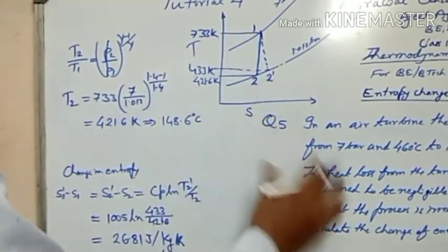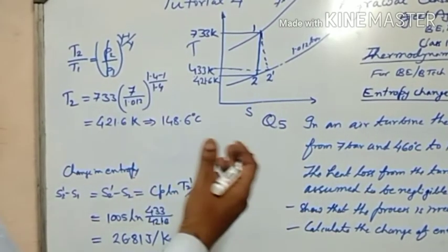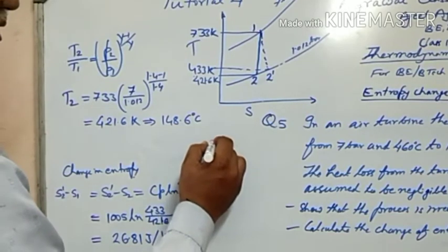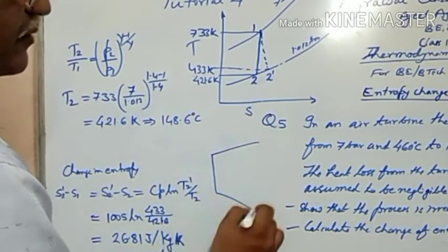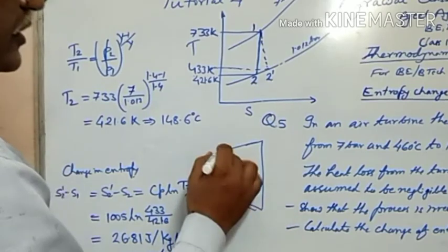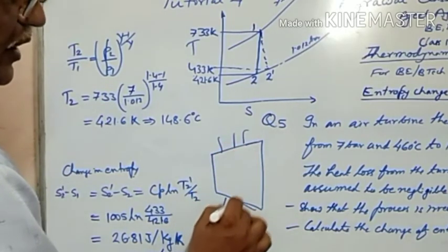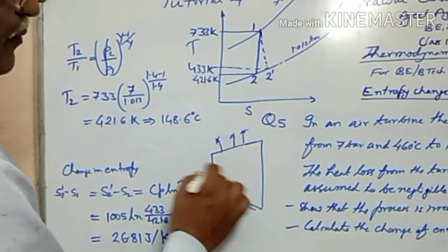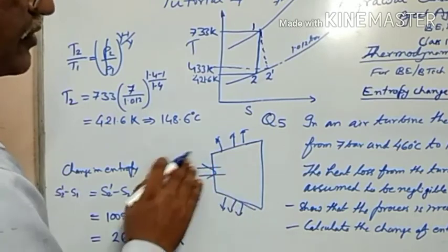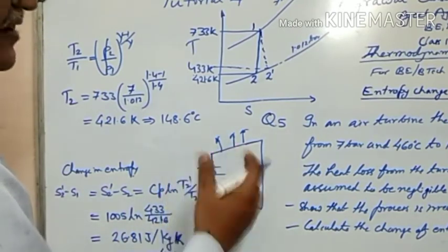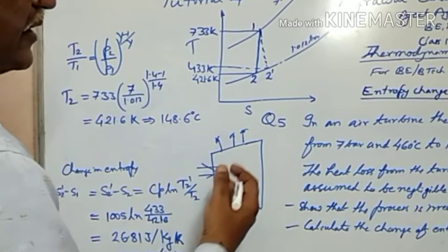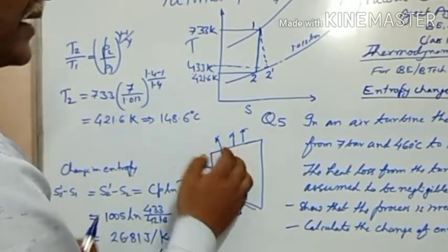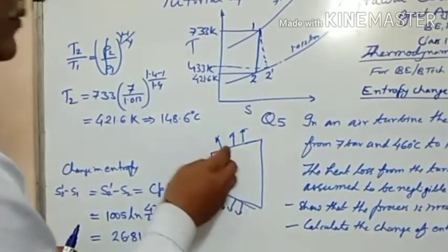And then as this process is adiabatic, how come this temperature has increased? So what actually happens in the turbine when the air expands? Although there is no heat loss going out, no heat transfer, the fluid, the air which is passing through this turbine, has viscosity, and because of that heat is generated there, and that heat is taken away by this air only, or this fluid only.